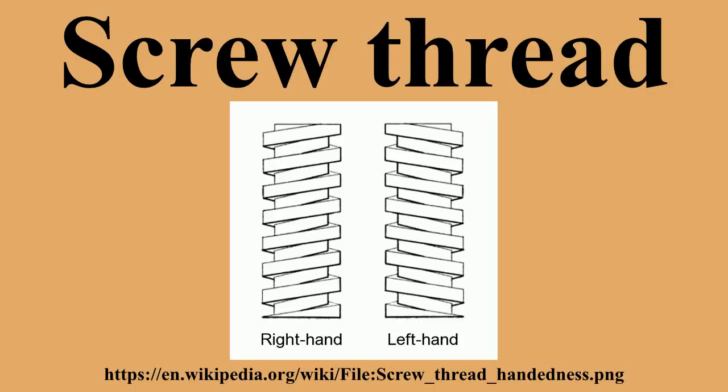Most triangular thread forms are based on an isosceles triangle. These are usually called V-threads because of the shape of the letter V. For 60 degree V-threads, the isosceles triangle is more specifically equilateral. For buttress threads, the triangle is scalene. The theoretical triangle is usually truncated to varying degrees.